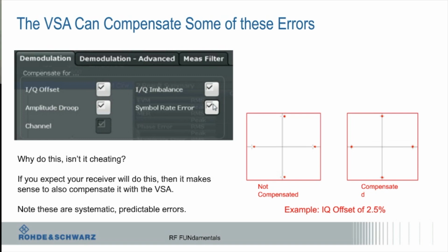And typically, a lot of people measure jitter on a scope, an oscilloscope, and what's nice about measuring jitter on an oscilloscope is it doesn't have to be a periodic signal. So if I'm looking at data jitter, data-dependent jitter, that signal isn't necessarily 10101010.